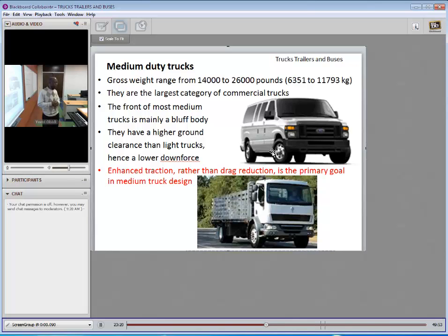And when attention is put to the design, whenever there is a conflict between creating cooling environments, cooling architecture for the front, for the fascia, and aerodynamic design, cooling goes first, because it's basic to the functionality of the vehicle.